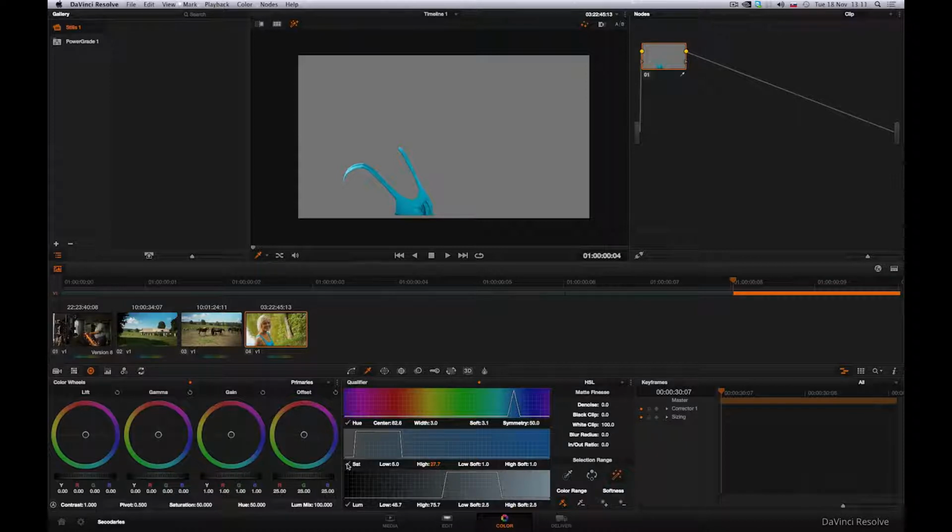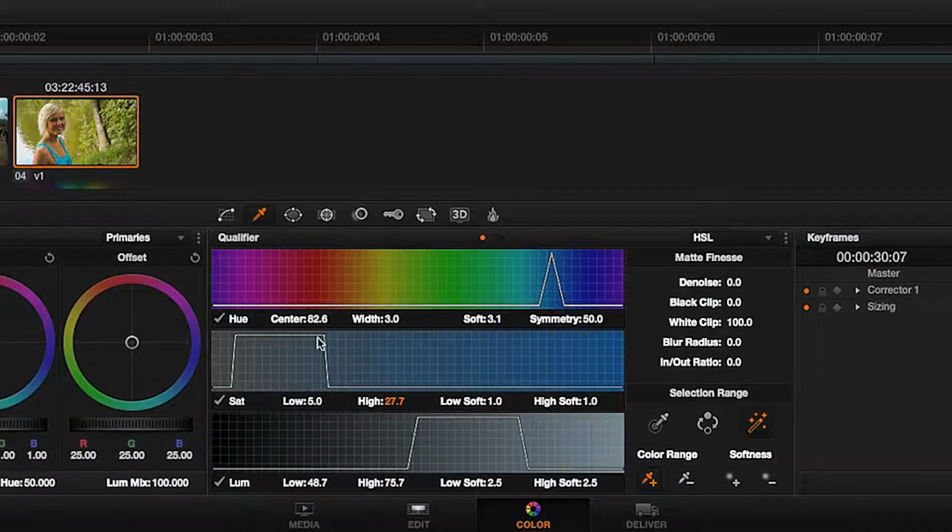In the selection, all areas in the upper part of the graph are set to 100%, and at these spots, the selection diminishes all the way to 0%. To further specify our selection, we can also use manual value input. If, for example, we'd like to extend the hue range, I can do so here. If we wish to refine the selection and add softness, we do so using this parameter.